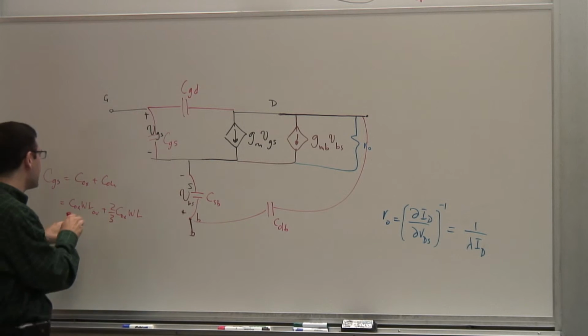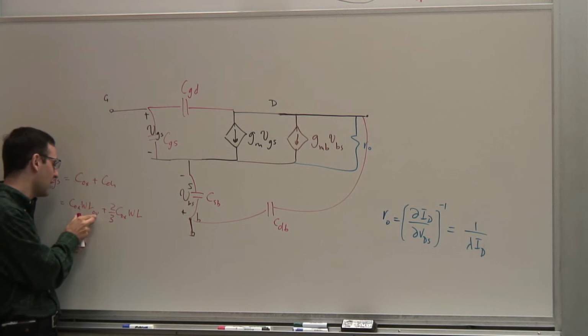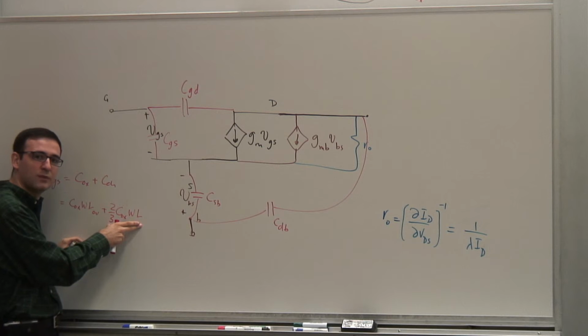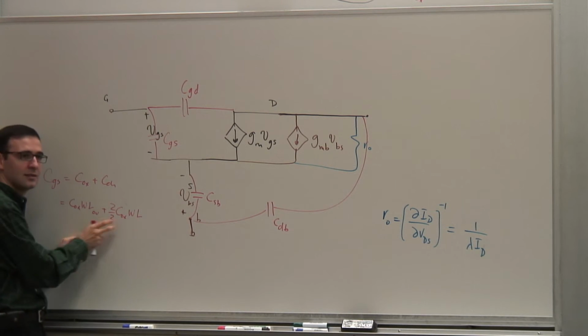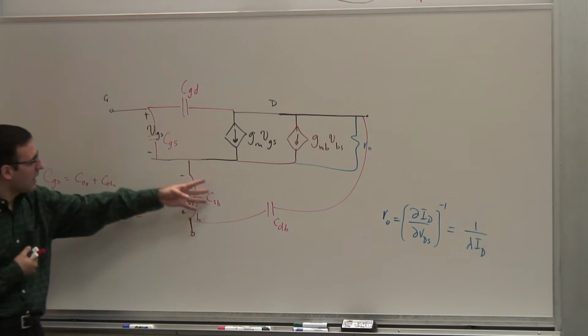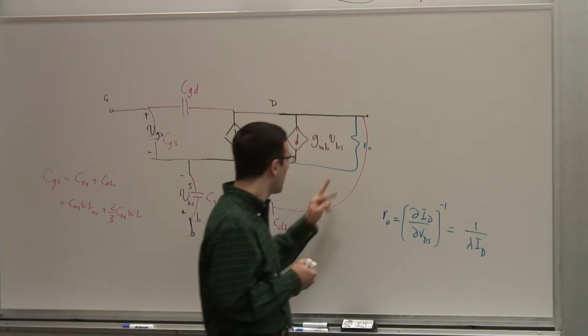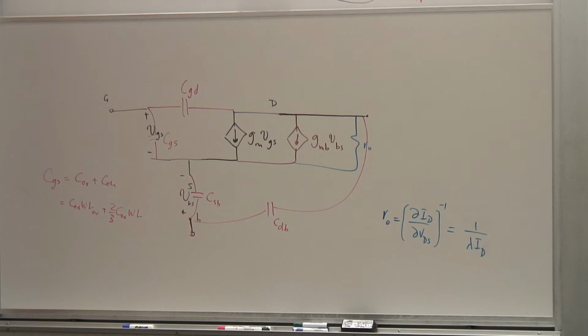Thinking about it, this has some similarities. There's just similarity here to the junction capacitance in the bipolar transistor, and this one to the diffusion capacitance, the base charge capacitance, CB. Similar to that. These two terms. Okay, so those are my capacitors, and that's my equivalent model for a MOSFET. So I have these 4 capacitors, and I have these 2 transconductors, and the RO. Now, I can calculate one thing.